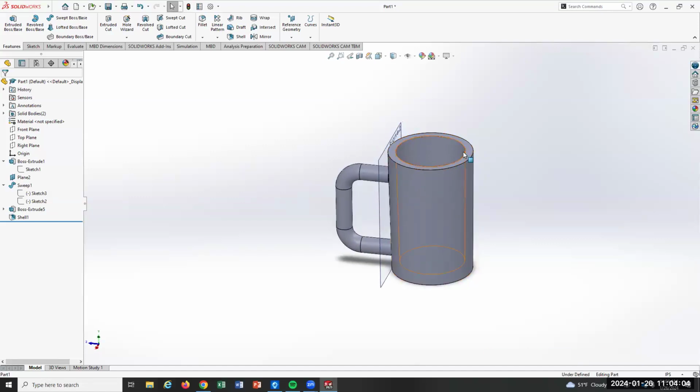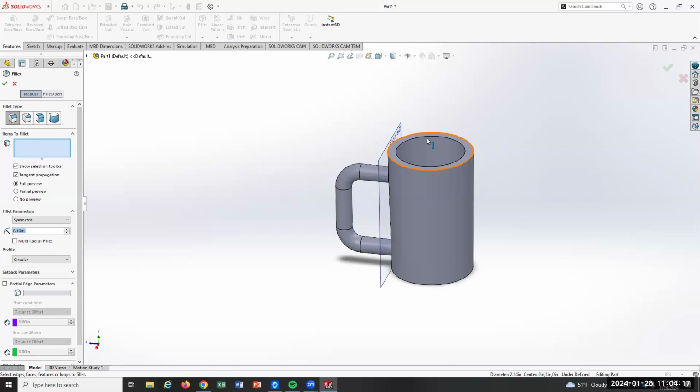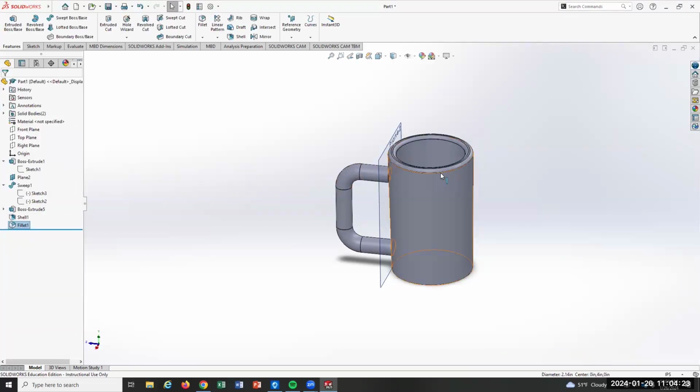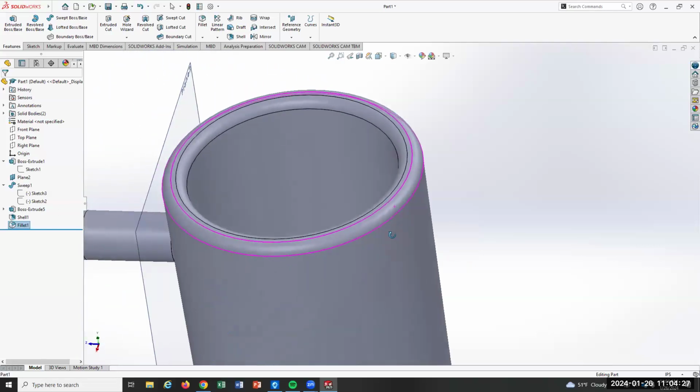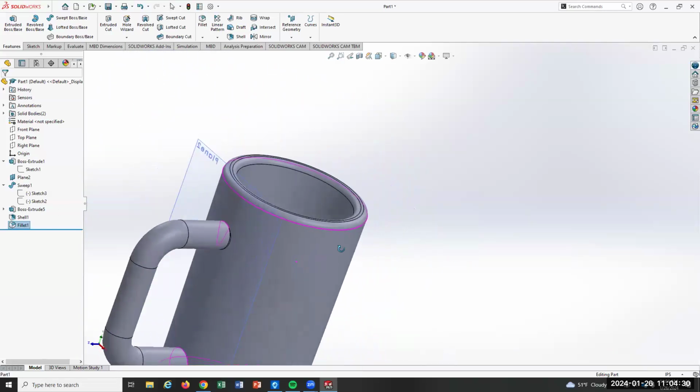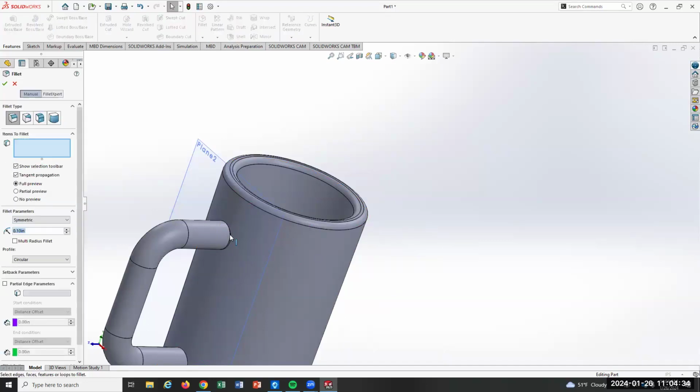And you could add some fillets. Just make it pretty. You can add a fillet to these top rims. So in features, there is a thing called fillet and it rounds corners, right? So if I grab this thing right there, it'll round it up, maybe the outside. So just to give you an example, it gives it a look like that. Kind of nice. You can round up transitions. This could blow it up, so try it.